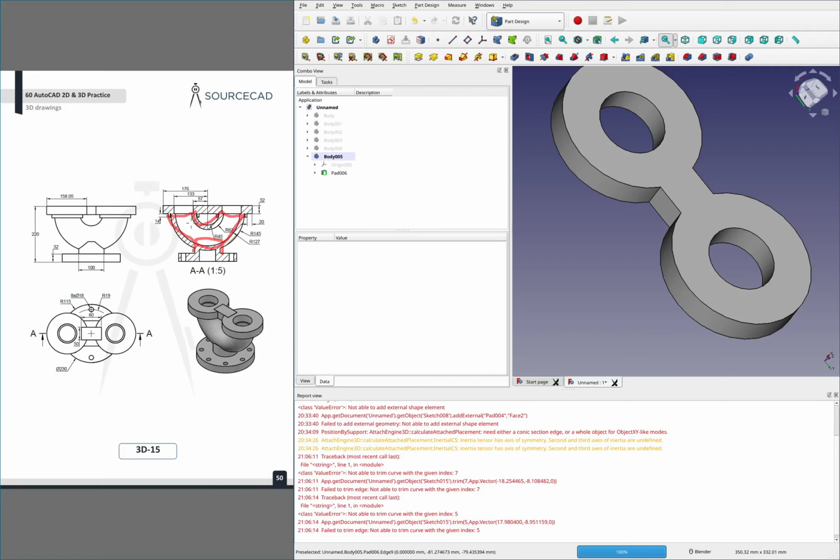Otherwise, if I did it the other way, so if I did the sweeping cut first, and then I extruded this up, I'd have to worry about lining the extrude for this bit up with this funky curved surface. So that doesn't seem like it would be much fun. So I think you can use the, let's see, the up to surface command when you go to pad something.